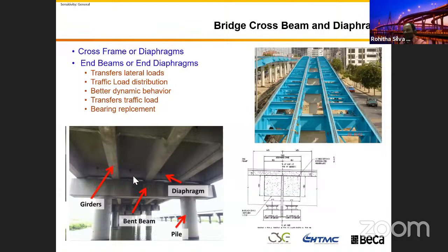Then, with the position of the bearing, you are supporting the bridge from your cross beams, not from your girder. If you want, you can detail a wider headstock. You can jack from the girder as well, but it's not that economical.